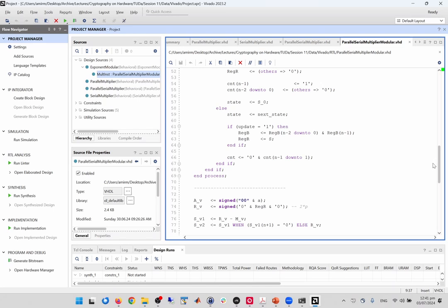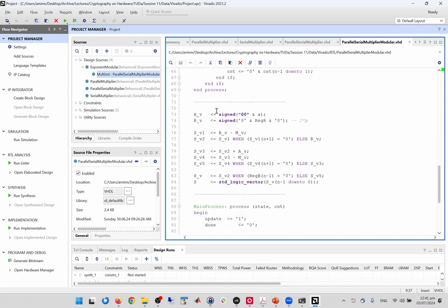And it performs the same thing as before with the serial parallel multiplier, but instead of this adder that I have explained, you see here I implement 2p, or multiplication by 2 of p, and then also check whether this is larger than the modulo, and then again I perform the addition we have seen in the slide, and then again check whether the output should be reduced or not. And then the sum will be provided.